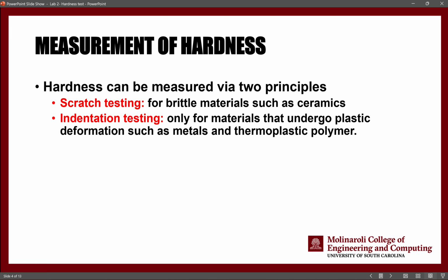But for materials with a long range of plastic deformation, we usually do indentation testing, which is the testing we are going to perform in this lab. So very important, if you want to do indentation testing, the material you're using should be able to undergo plastic deformation. So essentially metals. And we are going to use indentation testing for rubber-like materials. You have to keep in mind that the indent we create in the rubber-like material is a temporary indentation. So when you remove the hardness testing device, the indentation will go away.